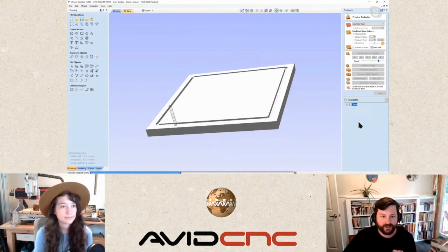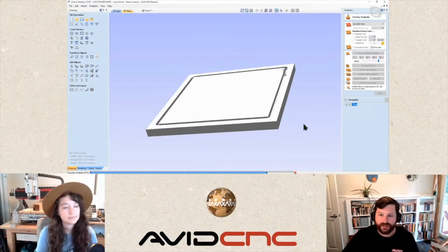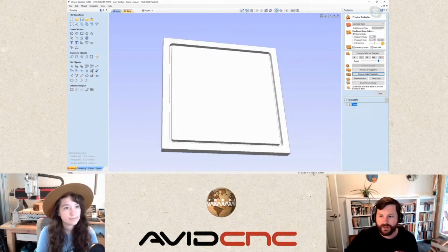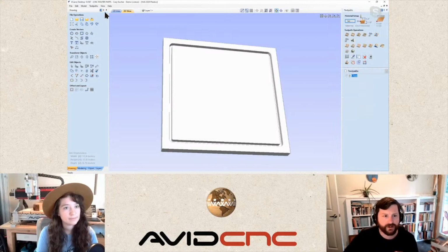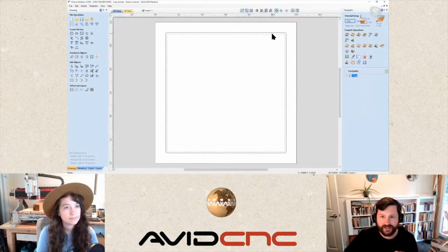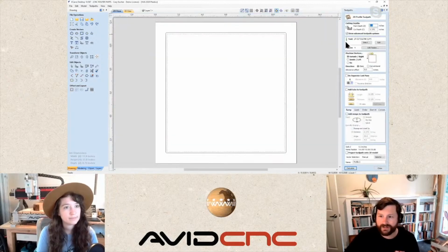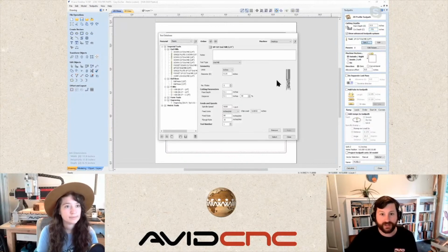And you can see we're starting in the lower left-hand corner, and we're creating this clearance toolpath. Then to create our final toolpath for our 10-inch, we're going to go back to this, and we're going to start at 0, but now we're going to go to 0.775. So we're going to go 20 thousandths beyond our material thickness. We're going to use that same 1/4 inch upcut end mill, to try to get those chips out of this canyon we're creating. We've got that same chip load. All of those settings are the same.